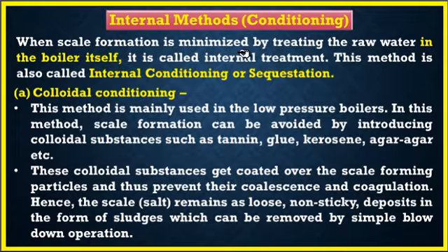When scale formation is minimized by treating the raw water in the boiler itself, then these methods are known as the internal treatment methods. These are also known as conditioning or sequestration. So basically the internal methods are those in which boiler feed water is treated in the boiler itself. So these are the internal methods. First internal method is the colloidal conditioning.